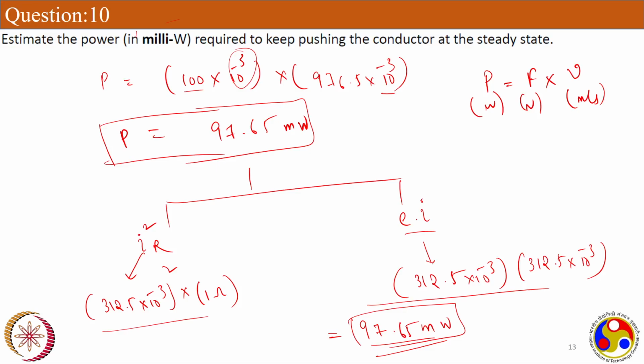No. That's electrically coupled circuit versus magnetically coupled. Even if there is a physical connection or not, if a mutual inductance exists, if you see two dots, then definitely mutual inductance will be present in that circuit, and based on that only you have to decide the polarity of voltage, not based on the physical connection. Okay. Thank you, sir. Welcome.